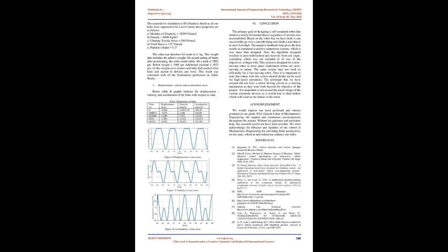V. Simulation and analysis. A. Isometric view. From this view, one can get a clear understanding of how links are assembled and components are placed. Wheel trace, Fig 11, and chassis trace, Fig 12, indicate the movement of the system going over the bump, in which the chassis remains horizontal/parallel and reflects almost negligible error, thus achieving our purpose.